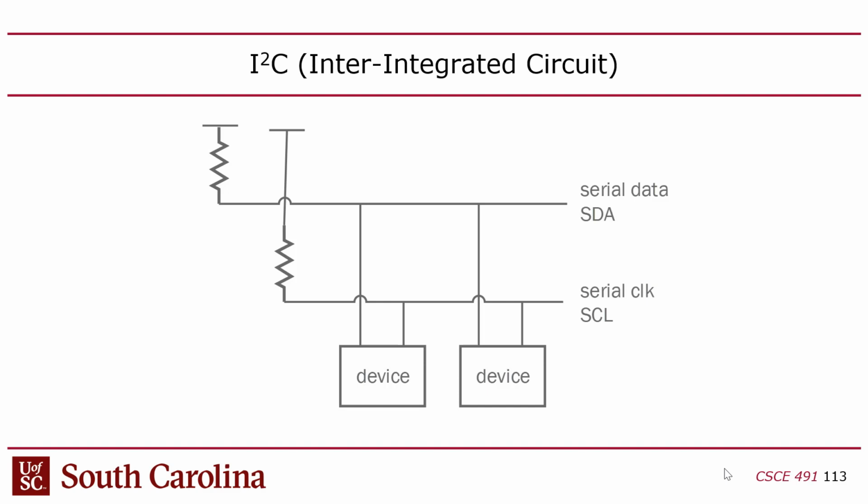So I2C says, look, because this is designed for a transaction type protocol where I'm reading or writing, where I have to send the address first and the data comes next, might as well just have a half duplex, 1 data line. And then there's no slave select because I2C, instead of slave select, uses basically a start bit, stop bit style interface like UART did.